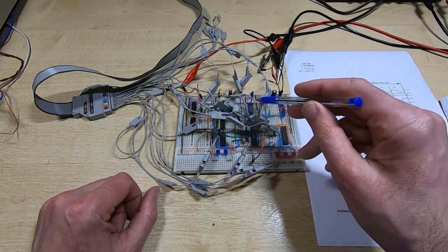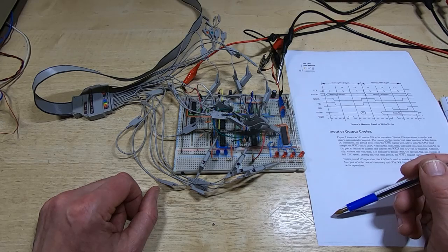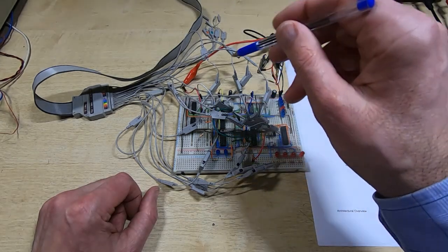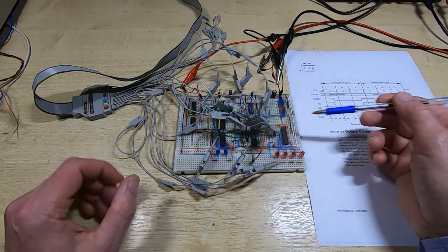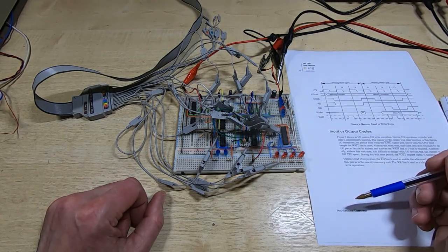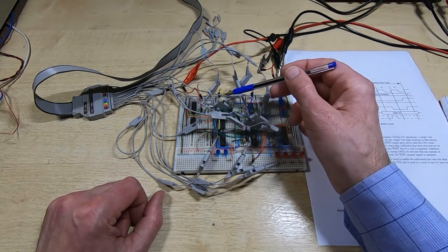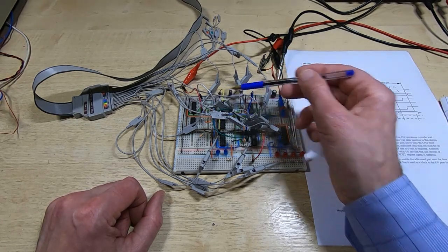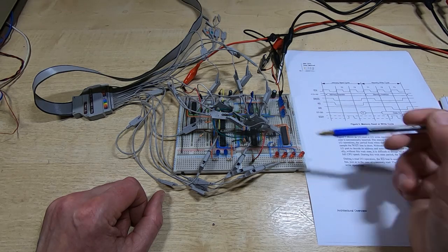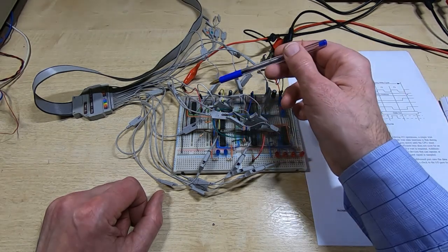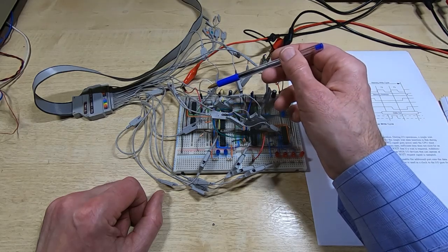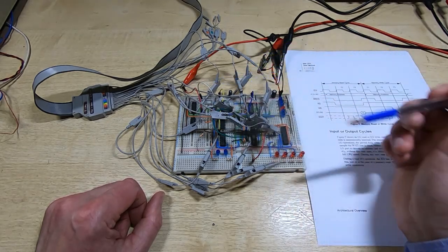So it will be automatic. As soon as the bus request line goes low, it will automatically start the process by giving us a bus acknowledge return. So all we have to do is take the input from the DRQ, send it high, and that will start the process running. This white jumper just sets the direction, whether we're reading or writing.